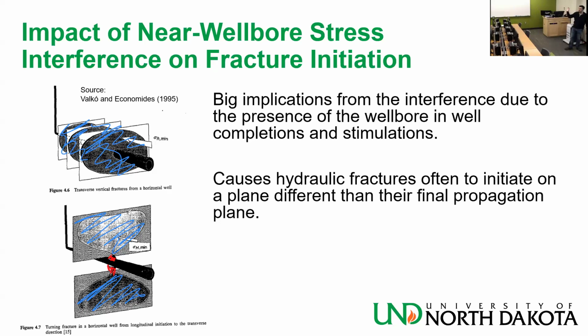Now, every time you pump a frac stage, when you go to the field, and we're going to talk about it more in module 3, most of the stimulation stages end up with a screen out, okay? You hit a situation where the pressure shoots up on the surface. You are pumping as hard as you can pump, but the pressure is not really transmitted downhole because there is an obstacle to the flow.